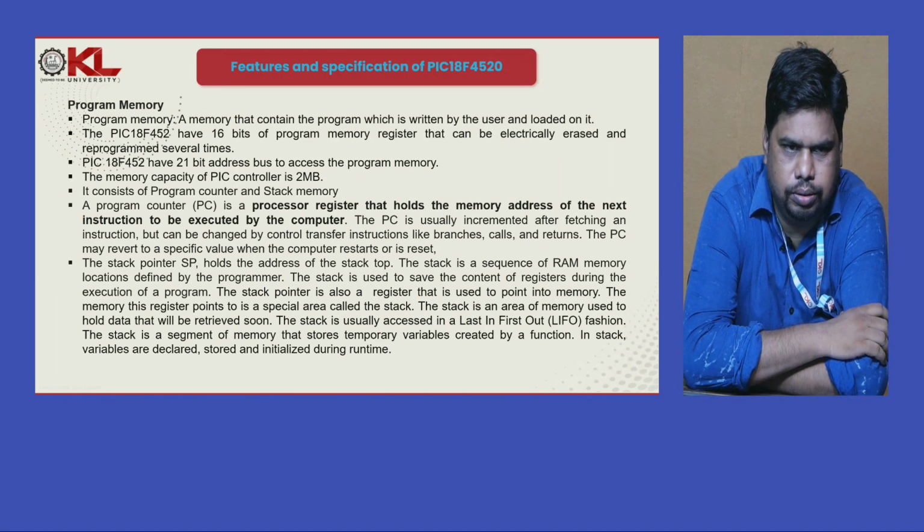It has 21-bit address buses to access this program memory, so the capacity is 2 to the power 21, that is 2 MB. The program memory section also consists of a program counter and stack memory.